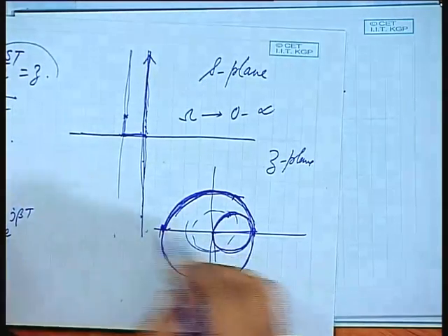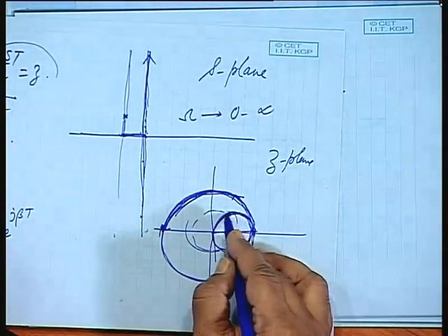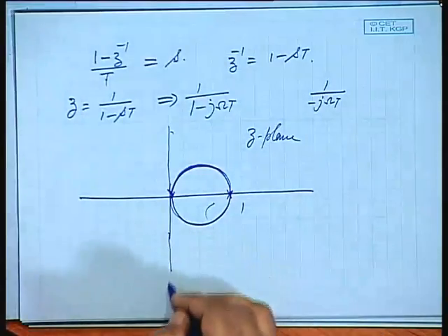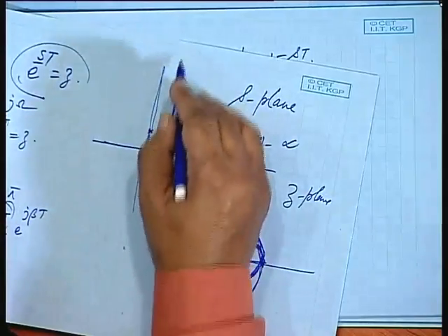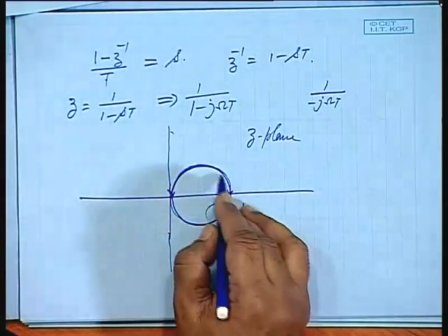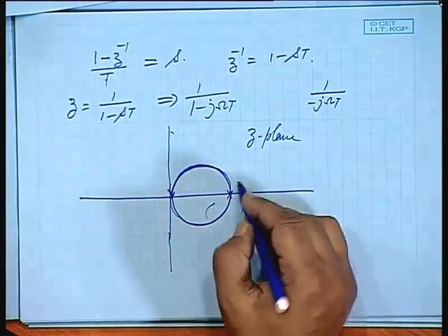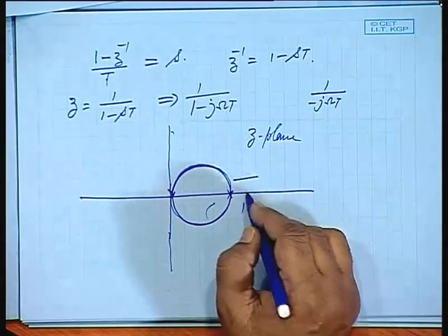but with this approximation I am constrained to believe that this is the stable region, because the mapping of the imaginary axis of the s plane is giving me this. So, it is a smaller circle, a very pessimistic, very conservative estimate. This point is conceived as an unstable point outside the stable zone, whereas it is not so in reality.